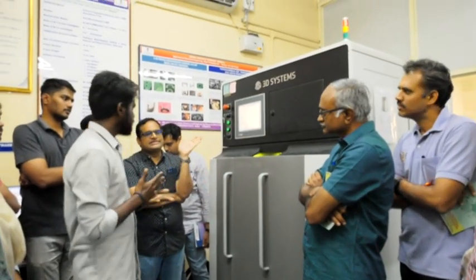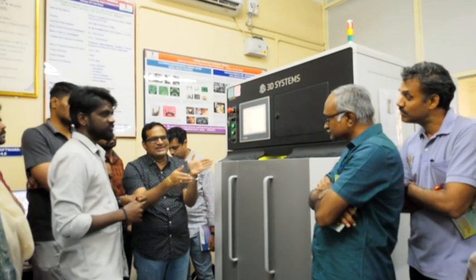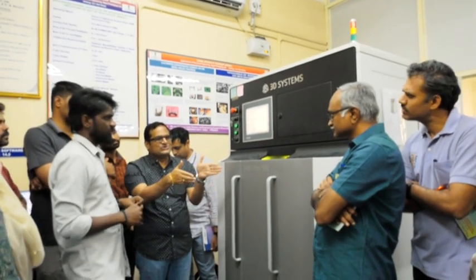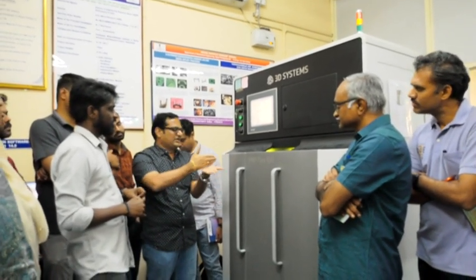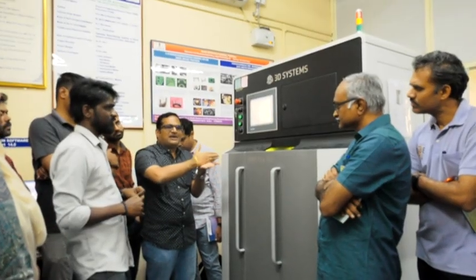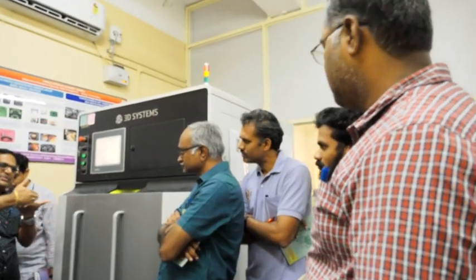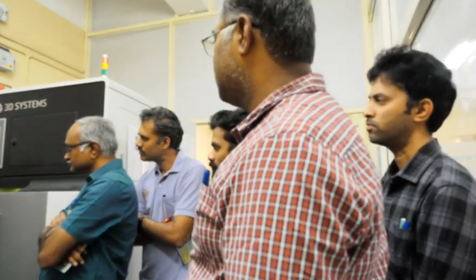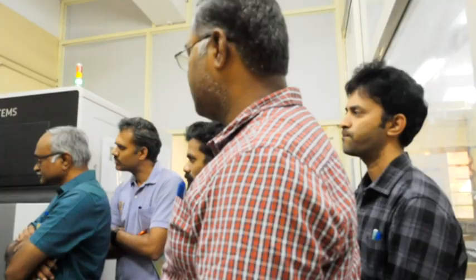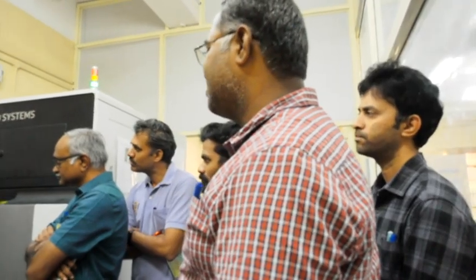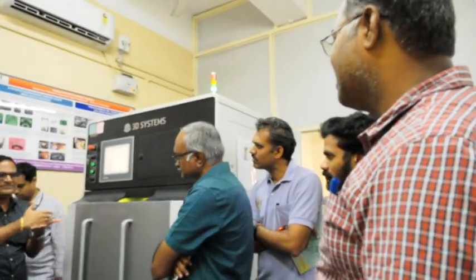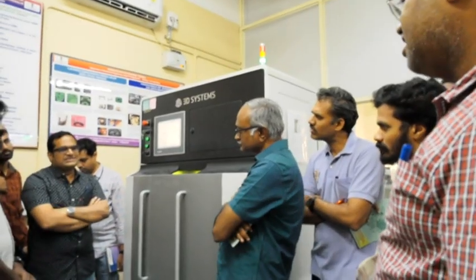Yeah, in my design for AM class, I told you how you can organize these. You should not put your roller and the part together. You try to minimize the contact area between the roller and the workpiece, which is why you maintain some 45-degree angle. So we need to follow all those guidelines. Otherwise, sometimes it will give you an error also. So we must be thorough in those design guidelines.